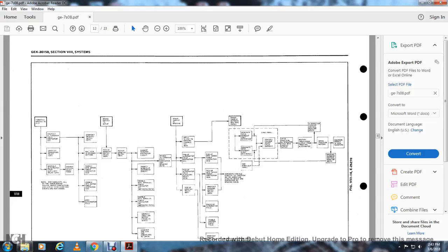It also goes to enabling the alternator field braking, which goes into braking handling and braking, which splits four different ways: to apply the 74 volts, I believe it's 74 volts, of braking control, pick up the alternator field current, the alternator field auxiliary relay, and pick up the braking relay.